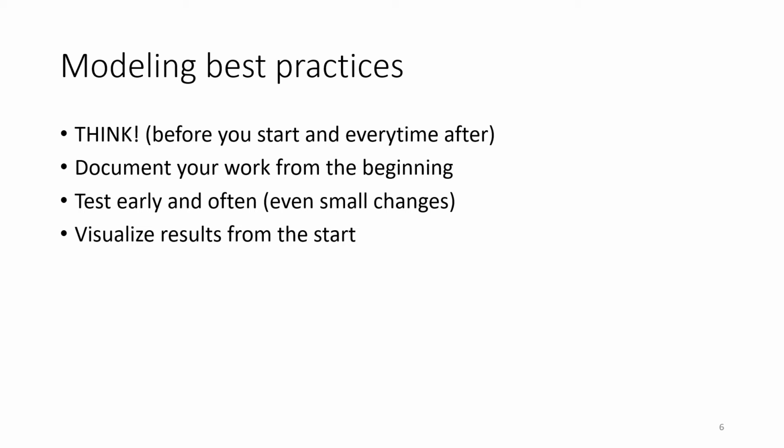And it's also reasonable, when you get experience, to think of, okay, what kind of result do I expect, right? If I have a very homogeneous region, I expect a very homogeneous pressure head distribution. And if something strange pops up, something I didn't expect, this is where thinking, okay, is there a mistake or not?